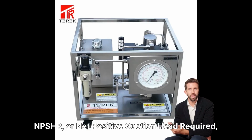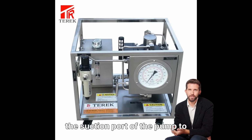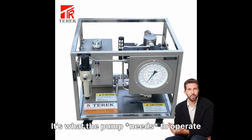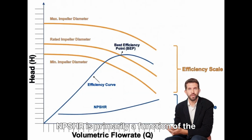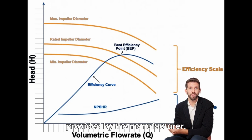NPSHR, or net positive suction head required, is the minimum absolute pressure required at the suction port of the pump to prevent cavitation. It's what the pump needs to operate without cavitating, determined by the pump manufacturer through testing. NPSHR is primarily a function of the pump's design, speed, and flow rate. It's typically found on pump performance curves provided by the manufacturer.